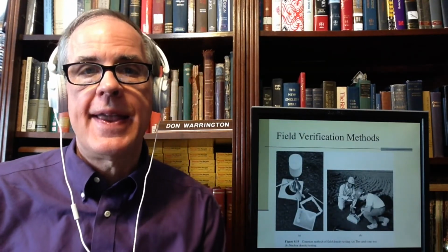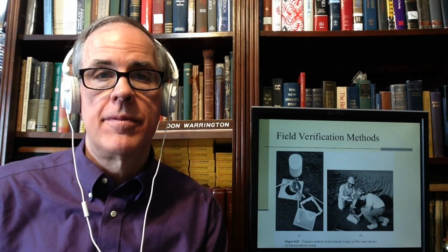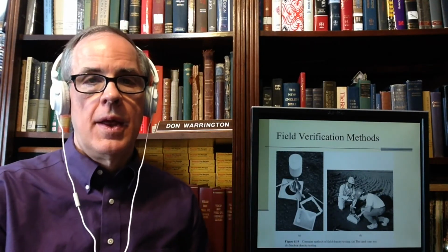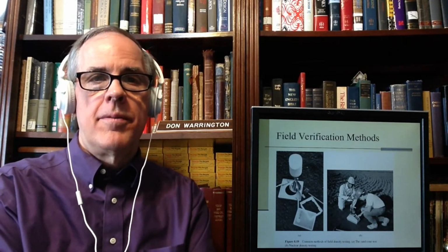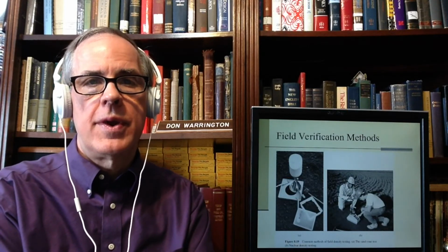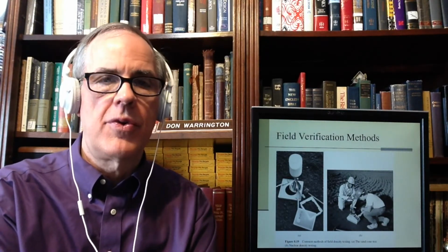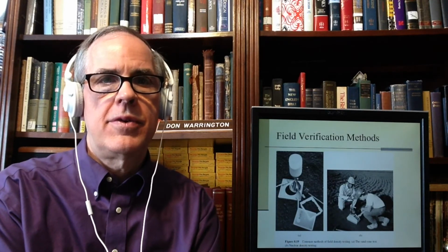Now we come into verification. Like I said, in geotech engineering we don't like to do things without proper verification. And that's certainly true with compaction. There are two basic methods we use. The most popular are the sand cone and the nuclear density test. Now, a little history, UTC history behind that, I'll go into. Back about 20 years ago, we didn't have a soils lab until I think it was 2005.